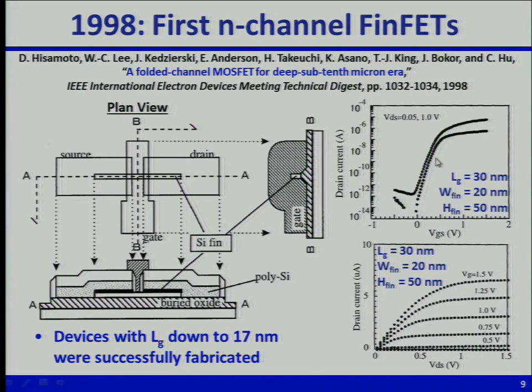And notice, what am I showing here? This is a plot of the current for low drain voltage and for high drain voltage. So what does this shift represent? DIBL, right? Okay, so remember I mentioned DIBL, no more than 100 millivolts per volt is actually what the industry requires.